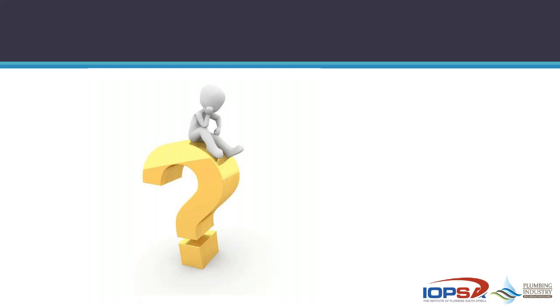The question should be that if it is the first and the last fitting, we need to do the testing. If you're going to be putting a torch and a mirror in there to do a barrel test, or putting your equipment in there to do a pressure test, you need access on those things, and the standard actually says that you need to provide those IE points for the access. When you're doing something like a gully, which you can't rod through, then an IE junction on the line is not a bad idea, because you could open that up and work your way back towards the gully.